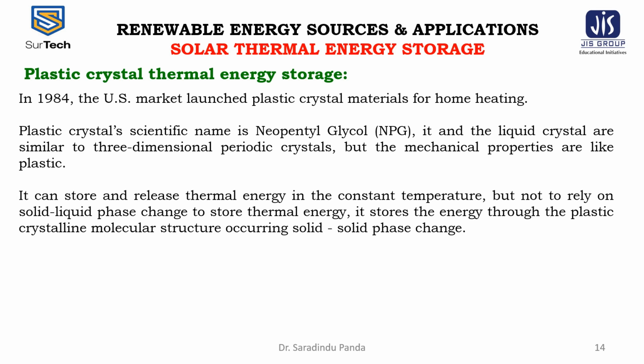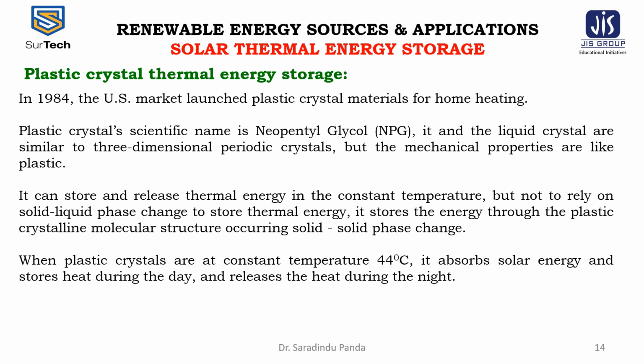So it can store and release thermal energy at a constant temperature, but it does not rely on the solid-liquid phase change to store thermal energy. It stores the energy through a solid-to-solid phase change in the plastic crystalline molecular structure. When the plastic crystals are at a constant temperature of 44 degrees centigrade, they absorb solar energy and store the heat during the day and release the heat during the night.